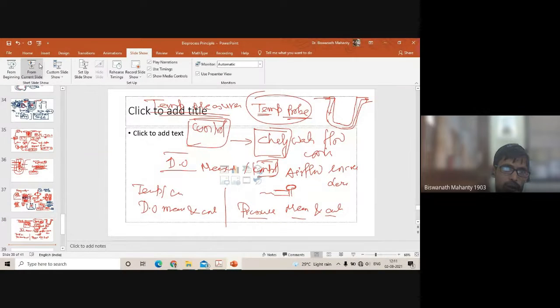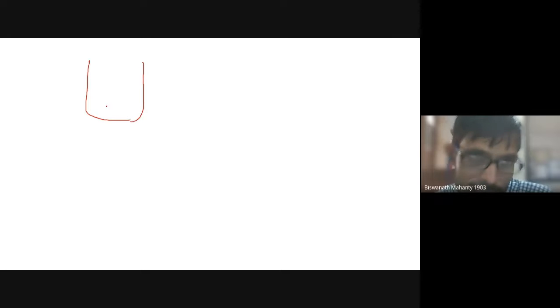So we are talking about different kinds, right? One kind can go inside. That means the sensor. Sensor means the element which is going to measure. So most of the time, your pH probe will come inside the liquid. Your dissolved oxygen probe will come inside. Foam will be at the top, it will not come inside: anti-foam measuring or foam measurement. Similarly, a pressure transducer will never come inside. We may have simply a pressure gauge.